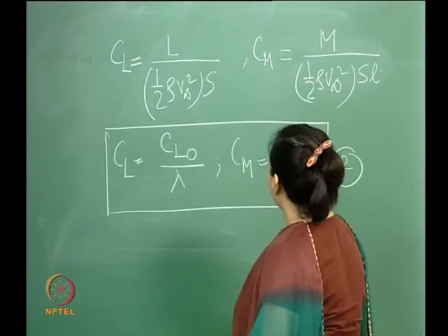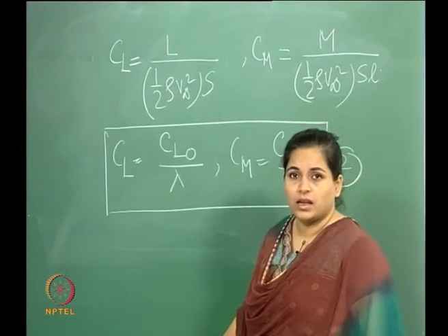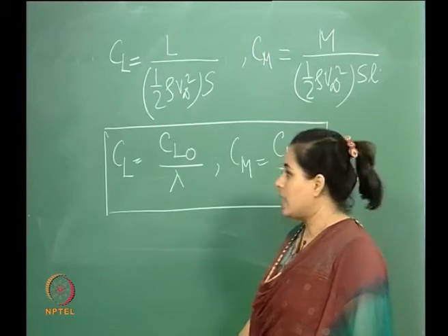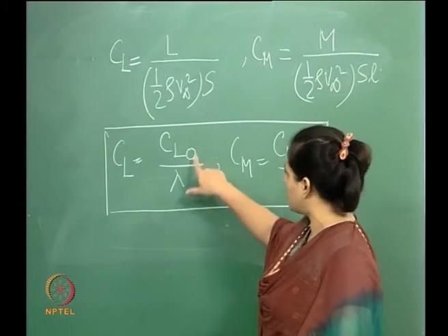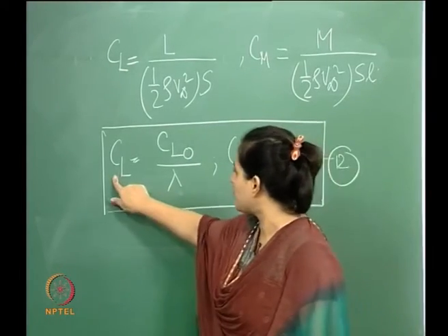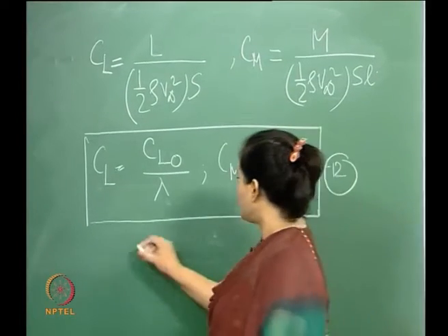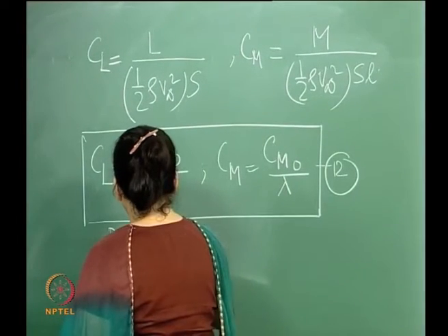So, basically what we do here, these are the two incompressible Cl and Cm, right, and this is the Prandtl-Glauert correction to it. You can add this correction to it and use it as the compressible Cl and Cm over the same profile.